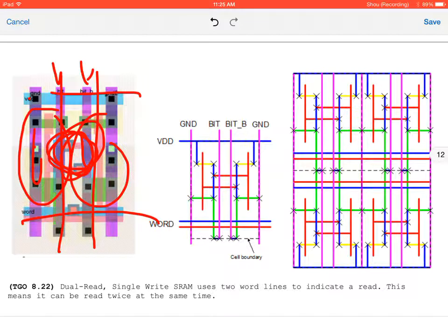So if you were given a stick diagram, you draw this out. You can see your first inverter. You can see your second inverter. You can see there's different metals now. So we have purple, the same as VDD and ground in terms of color for metal 1. You have your poly, right? And your poly is here. You can see that the poly from the input here is the same as the output of the inverter. So this is where the loop comes in.